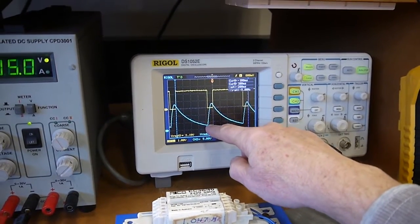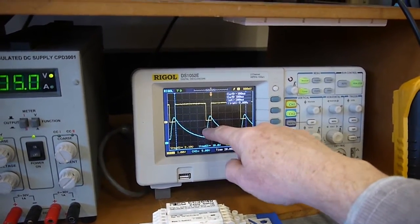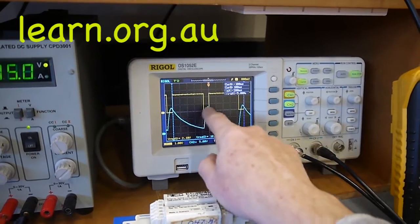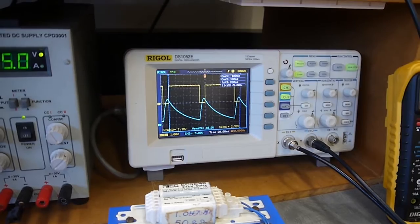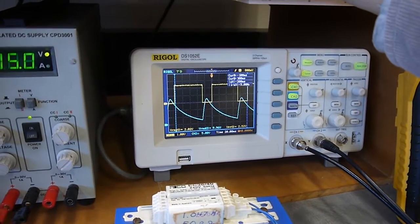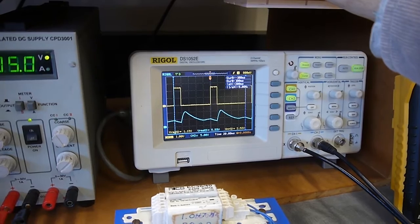If we look at the average there, we've got 3, we're going up to about, is that 5, 10, 15, we're at about 9 volts or something there at the output, even at that low frequency, because the on time with the duty cycle of the pulse is still quite long. And I can reduce that duty cycle down, even at that low frequency, back to 50%, and you can see the effect on the output there.